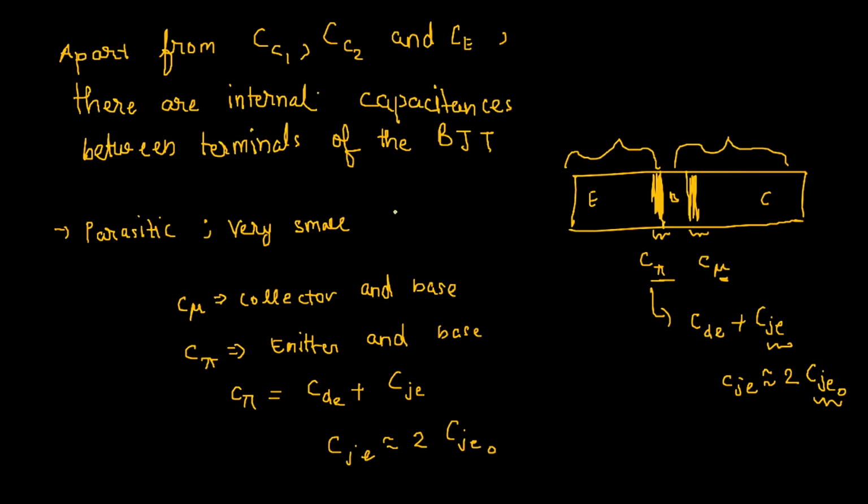What they actually do is reduce the amplification, the voltage gain which we actually get. Like I said, these capacitors don't always act. In most situations they are short circuited, but in the situations where they act, they really reduce the amplification of the device.